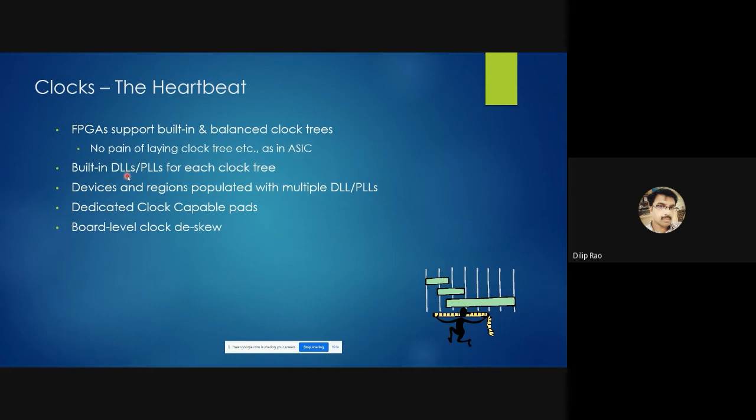It will come with its own jitter, its own noise, and its ramp time and slew rate will be affected. All these clock characteristics need to be corrected. For that, we have specific deskewing elements built into the device. Their functionality is to clean up the incoming clock and make sure that a very pure clock waveform is fed into the rest of the design.